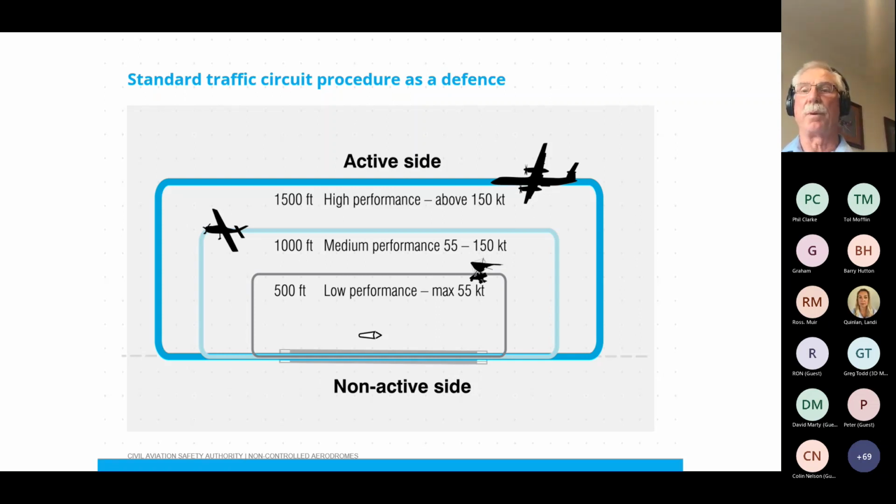So yeah, it is something that people need to be much more aware of. We have a base up at Bendigo, and we have RPT aircraft coming in, and that's one thing we're very, very mindful of with the students up there, is to get them to appreciate how much extra space they'll need on the downwind leg, and therefore leading to a wider base, and that then has implications for where they may or may not be able to turn base.